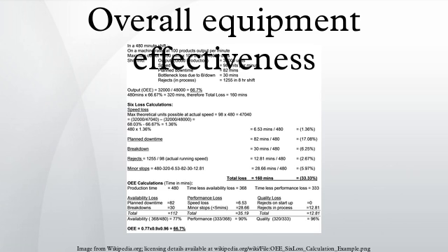The underlying metrics: in addition to the above measures, there are 4 underlying metrics that provide understanding as to why and where the OEE and TEEP gaps exist. The measurements are described below. Loading, the portion of the TEEP metric that represents the percentage of total calendar time that is actually scheduled for operation. Availability, the portion of the OEE metric that represents the percentage of scheduled time that the operation is available to operate, often referred to as uptime.